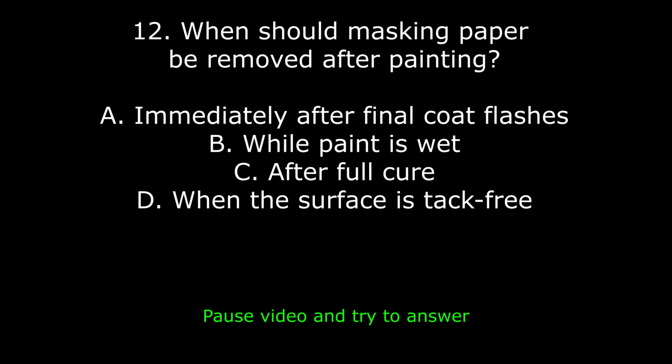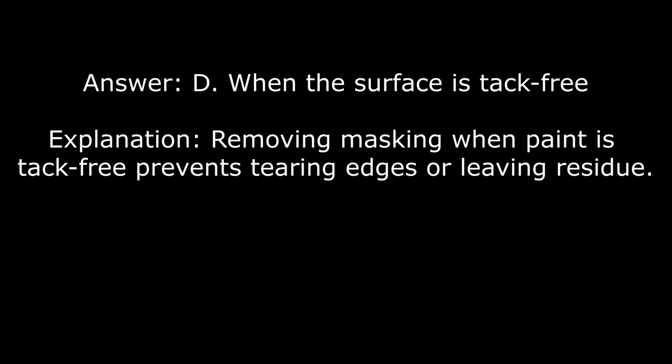12. When should masking paper be removed after painting? A. Immediately after final coat flashes. B. While paint is wet. C. After full cure. D. When the surface is tack-free. Answer: D. When the surface is tack-free. Explanation: removing masking when paint is tack-free prevents tearing edges or leaving residue.